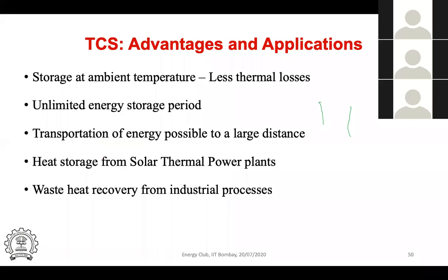The basic advantage of thermochemical storage is that you can store energy for a very long duration, even for 1 year, which is not possible for any other type of energy storage. If you are able to insulate this thermochemical storage well, then you can store that energy for even 1 year, 2 years. This is called seasonal storage. In France or Spain, when winter comes, this type of storage has very good application. During summer they store heat, and during winter they extract heat for say 6 or 7 months. So this storage is very good in that respect.